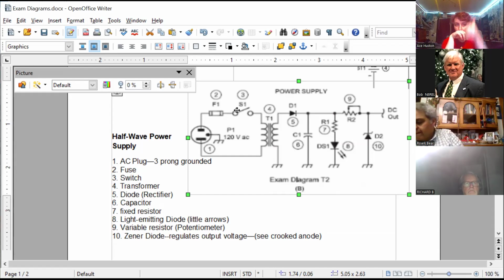This is called a single pole. It works on one conductor, and it's a single throw. It only goes on or off. Sometimes there's a choice. There's a pole here and a pole here, so it can turn on 2 circuits. If you live in a house that has stairs, there are usually 2 switches, one at the top of the stairs and one at the bottom.